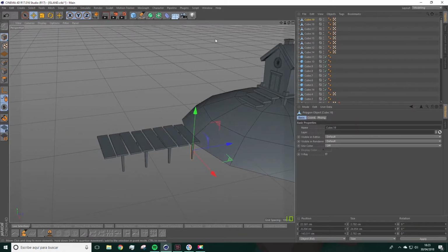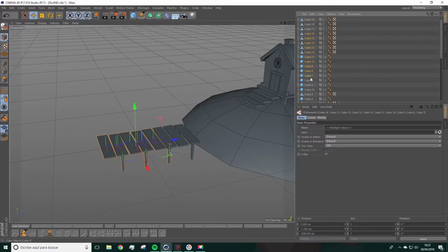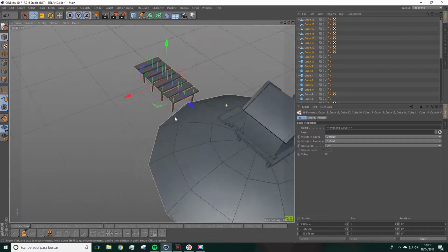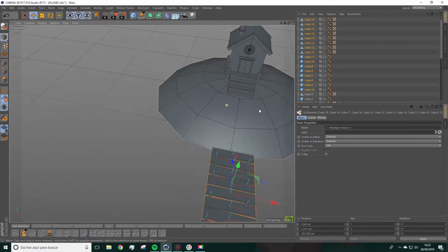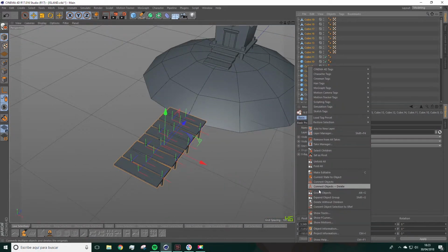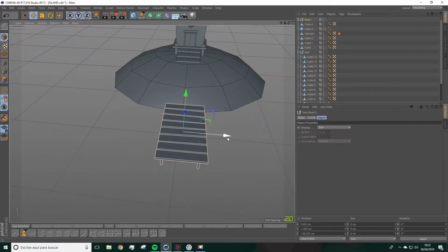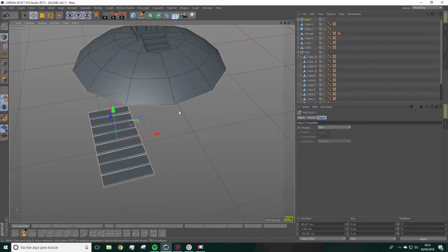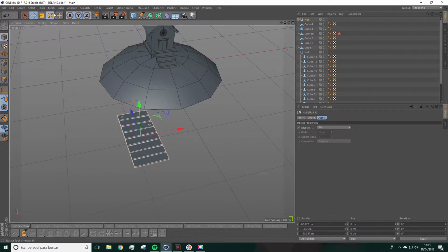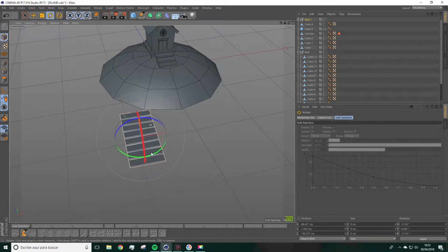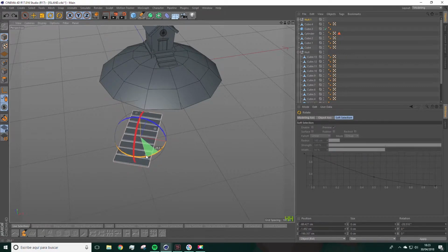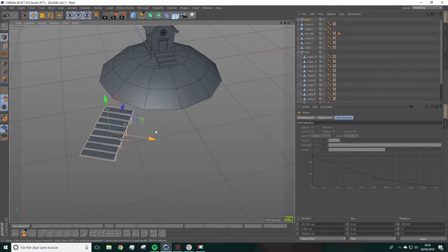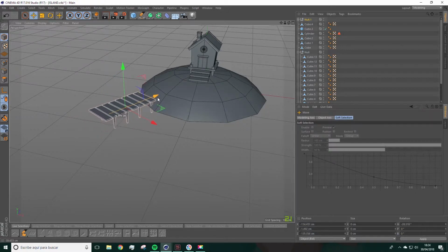Well, select all these elements and group them in an object group. While holding Shift, select from the first cube to the last one of the list. Then, right-click and click on Group Object. Let's rotate the whole structure and place it here. Okay. And here, for instance.